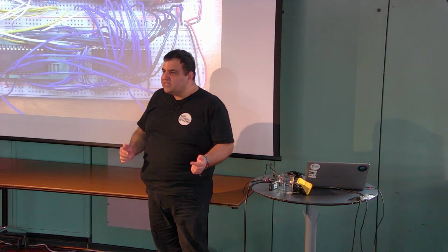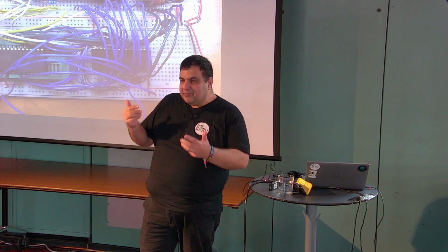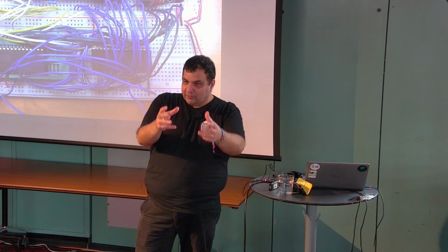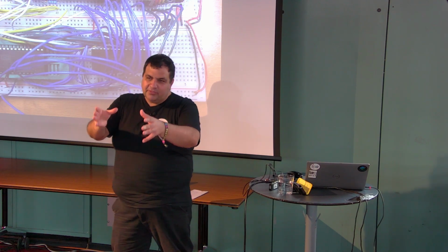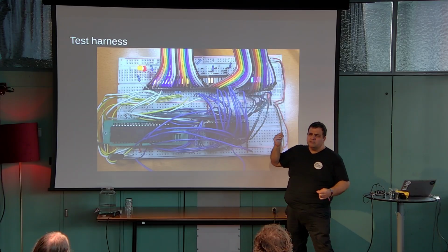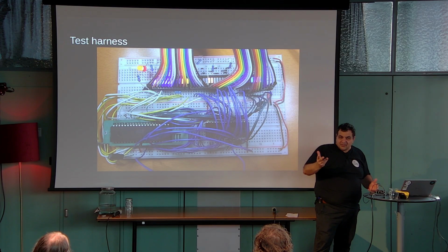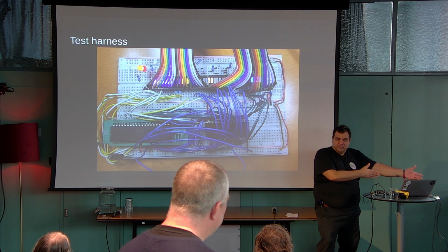And this is their demo project. The reason I picked it is because it's very modular. You say what you want in your component, in your RISC-V, and then it generates Verilog that matches that. I think the RISC-V is around 300 LUTs. So it's really, really tiny because I don't need a lot. If I wanted floating point, it would be bigger.